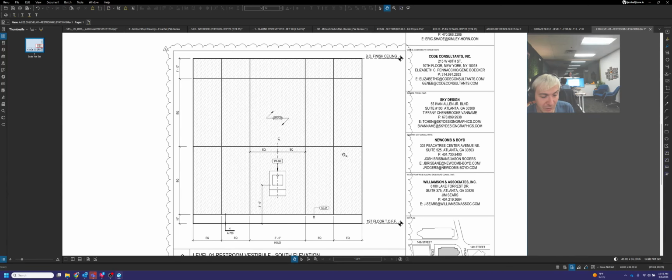It also becomes less manageable to install, because as you ship the panels and install them in the field, imagine you're dealing with a panel like this. This is 60 inches wide, so this is a pretty wide panel, 60 inches wide by however tall that ends up being for the EQ dimension there. This is going to end up being a pretty massive panel. It might be worth our time to suggest putting a reveal in the middle of the panel here. We can run that past the project manager on the job and see what they think, just to get within a more manageable panel size.